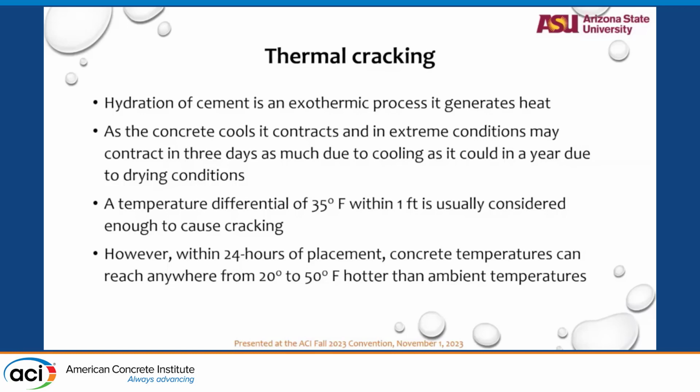When the contraction and expansion reach a stress such that the tensile strength of the concrete is exceeded, it cracks. It's generally assumed that a 35 degree Fahrenheit change on a 1 foot thickness of concrete is enough for thermal cracking to occur, and there's generally about a 20 to 50 degree Fahrenheit change in the cement itself due to the hydration.